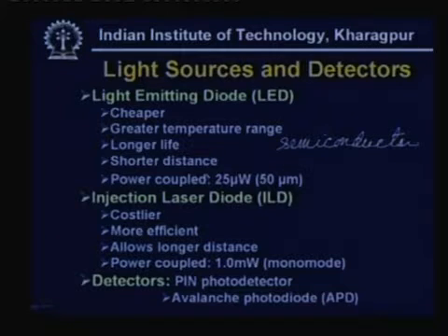However, because the power coupled is very small, for example, in case of 50 micron core diameter, the power that can be coupled is only 25 microwatt. As a result, it can be used for only short distance communication, and particularly it is used in multimode fiber.